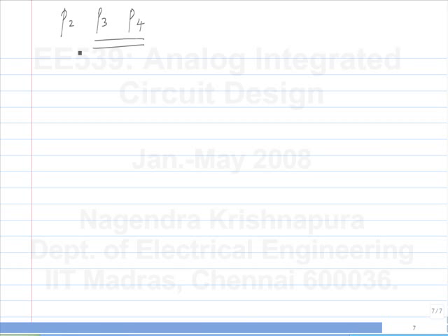So, one thing is you look at the values of the poles. If P3 and P4 are 10 times P2, maybe you can neglect them and assume that it's a second order system with only P2. Then make statements based on P2 that we already have done. But let's even say that I have 3 identical poles.